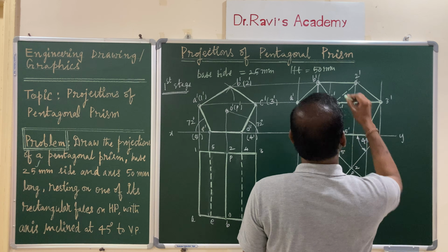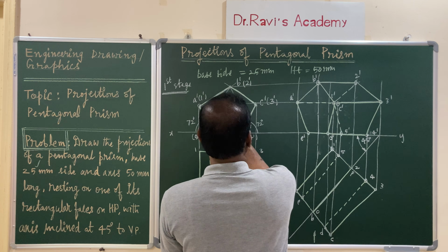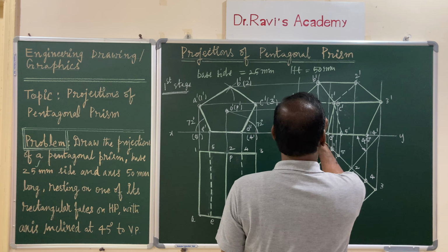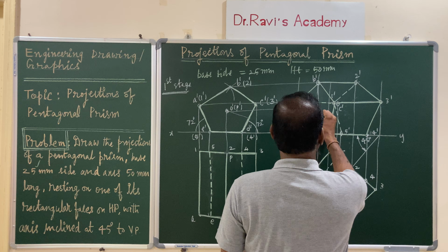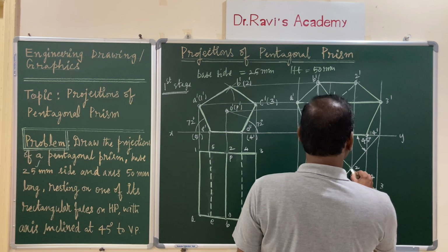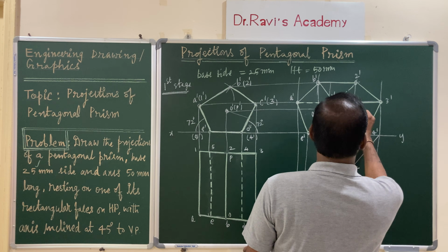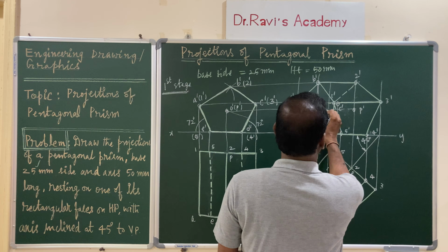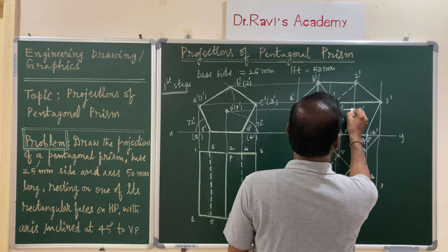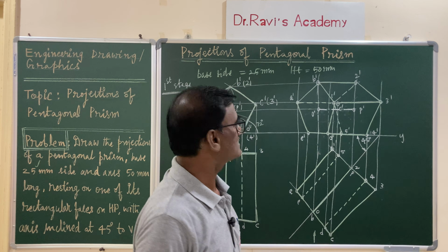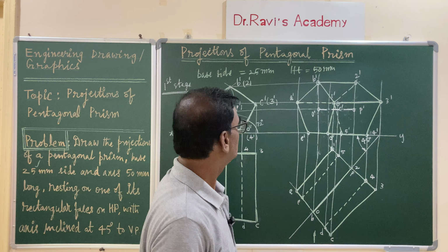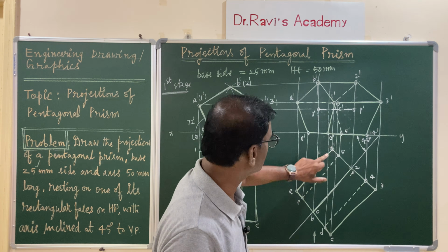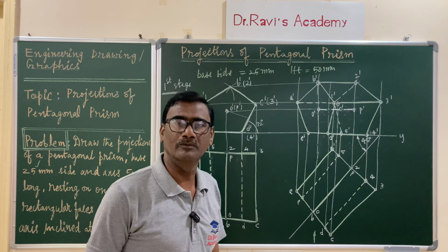And of course you can draw the projector from the axis also, OP, and this is O prime, and of course P prime, and this you have to represent with a long chain line with the 2H pencil. So this completes your problem. So let us make it very clear in understanding and draw it in a systematic way so that you will be able to draw comfortably.